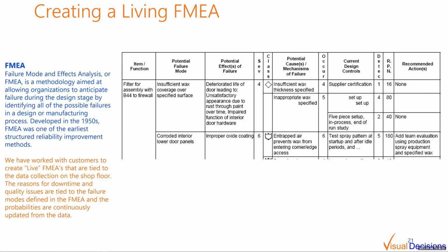You can also then utilize this to increase that probability of detection if I need to infer it from a couple of different things that are going on. You can utilize the analytics capabilities to use that machine intelligence to then infer that this is the particular failure mode that is occurring. And by doing this, I can actually keep my severity and my probability of occurrence live and up to date at all times, and essentially have a live FMEA.